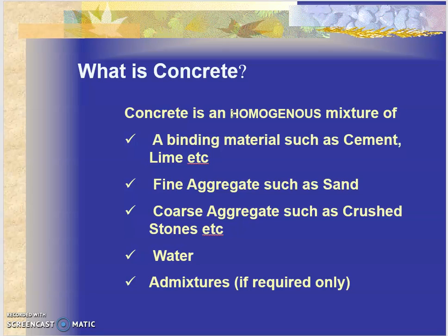What about sand and coarse aggregates, gravel? They do not participate in this reaction. They are the inert ones. They are only there to impart strength, hardness, durability. To a certain extent, they are also fillers, because just cement and water will be very costly, right? So to a certain extent, they are doing the job of inert fillers. And then admixtures are these chemicals which will alter the properties of this concrete.